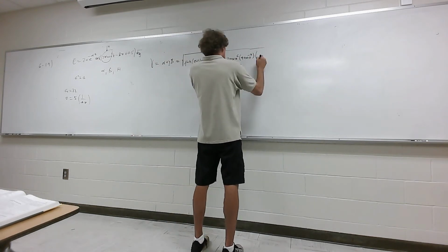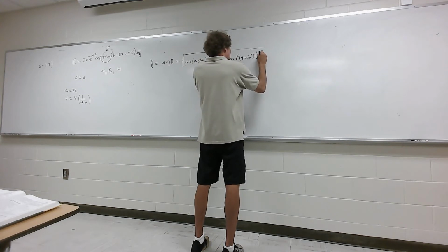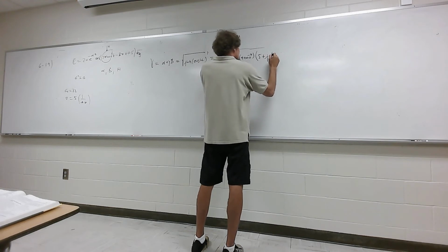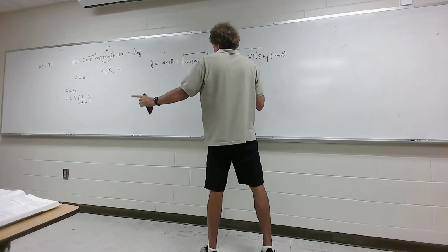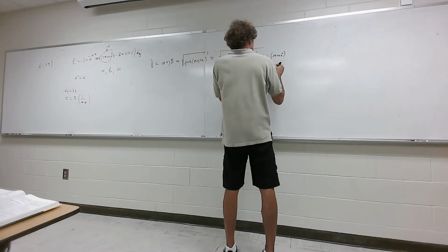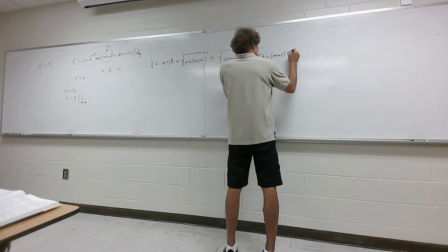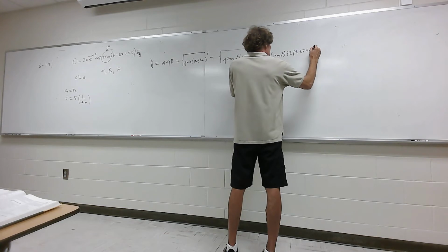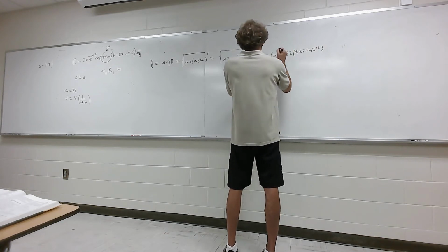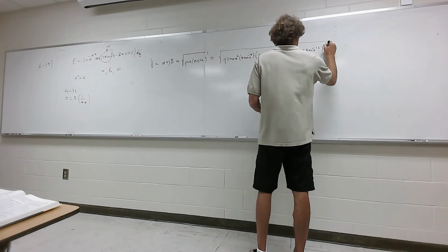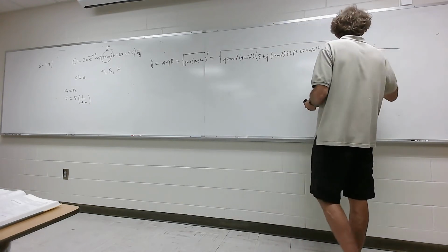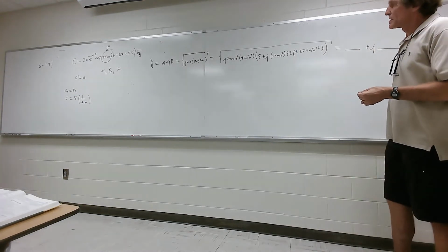Then you multiply this by sigma, which is 5, plus j times omega, which is 2 pi times 10 to the 6th, times epsilon relative epsilon naught, times 72, times 8.854 times 10 to the minus 12. Then I close the parentheses. So I'm going to get two numbers, alpha plus j beta here. Can you all do this for me?